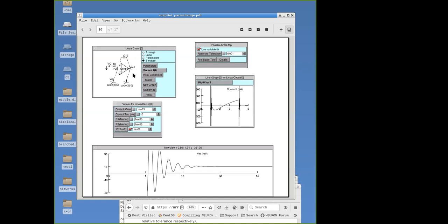This is reminiscent of something some of you may have been engaged in, ham radio. That used to be technology that was very fascinating before the advent of computers. Some people still are. And they would use what they call gimmick capacitors, which would basically be a pair of twisted wires with insulation around them. Just one or two turns gets a few picofarads of capacitance for the sake of stability or coupling when you needed a very small amount of coupling. Well, normally there is stray capacitance everywhere on circuit boards, everything, okay?